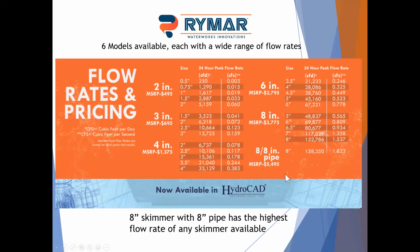So again, we have 6 models. They range from our 2-inch with a 1/2 inch orifice, which is a trickle, 250 cubic feet per day. I mean, that is minuscule flow. So we have 5 options in our 2-inch, 4 in our 3-inch, 5 options in our 4-inch, and our 6, and our 8. Our standard 8 uses a 6-inch pipe to connect the skimmer to the outlet structure. This is so we can reduce the weight some. We do have an option for our 8-inch with an 8-inch pipe. We sometimes refer to that as our 8-inch max.